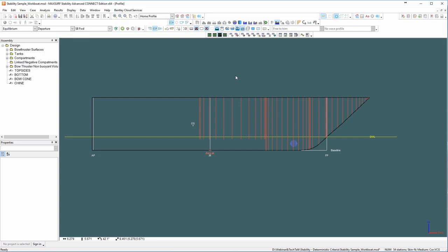In a lost buoyancy method, we remove a section of buoyancy from the hull that was occupied by the tank that has been damaged. The weight of the steel in the ship is still exactly the same, but the buoyancy provided by that ship has been reduced by the damage. In an added weight scenario, fluid flows into the hull and increases the displacement of the ship. In both scenarios, the ship will sink by the same amount.